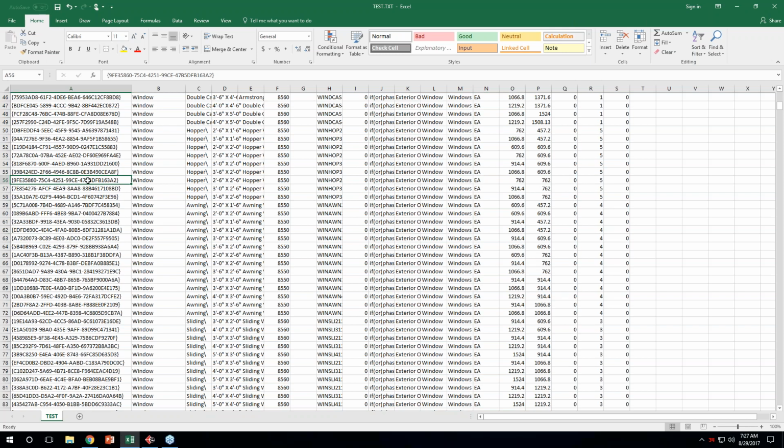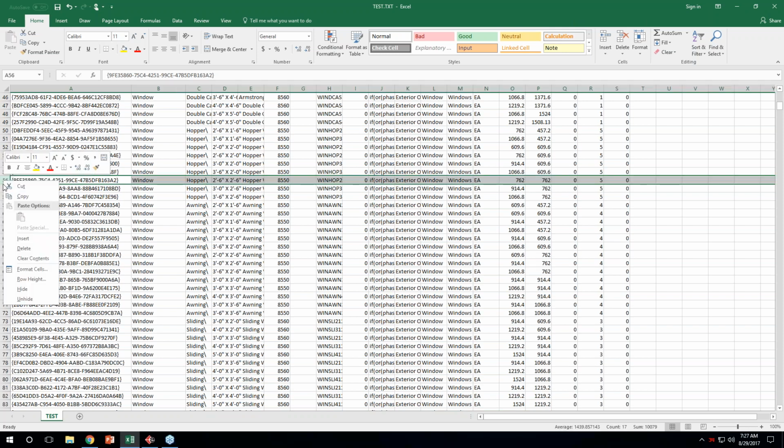With the same thought in mind, if I wanted to take that window and make a copy of it and add it into my catalog as well, I can create and copy this window, changing this ID number, and it will come in as a brand new element in my catalog. So you can update the existing elements by not touching this first column of information, or you can duplicate them to create new catalog elements on the fly in this spreadsheet and give it a new ID number so that it creates a new element automatically for you.